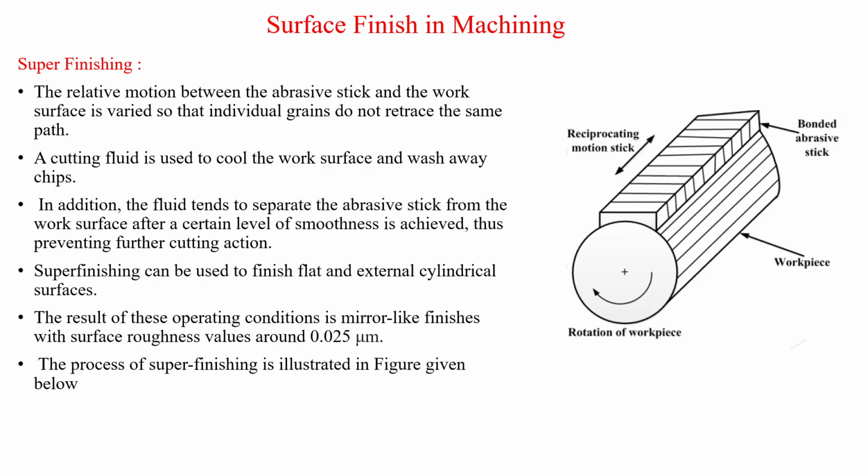You can see here this is the workpiece, this is the rotation of the wheel, this is the reciprocating motion, and these are the bonded abrasives. Because of the movement of the workpiece and the reciprocating motion, the abrasives interact with the workpiece and finishing occurs. Cutting fluid is used to cool the workpiece and wash away the chips, and it is used for finishing both flat and external cylindrical surfaces.